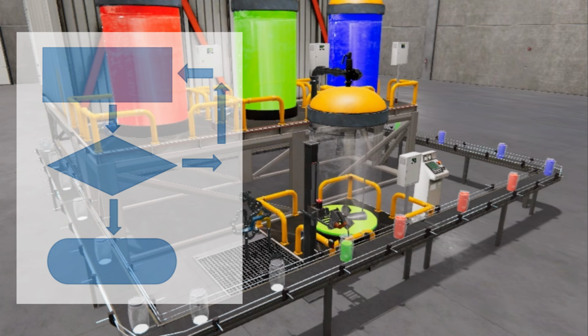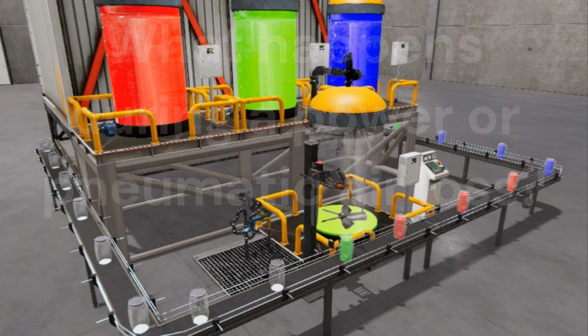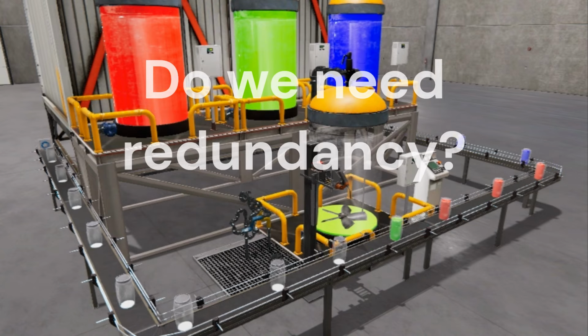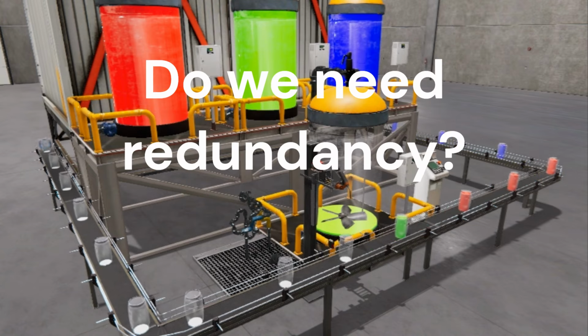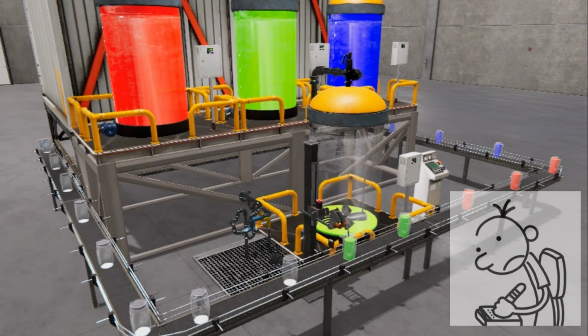This will help answer important questions about what happens during a power or pneumatic air loss or if any input-output devices fail. Additionally, it is essential to determine if redundancy is necessary. By understanding all aspects of the operation up front, you can save a lot of work and prevent the need to rewrite the PLC program logic continuously.